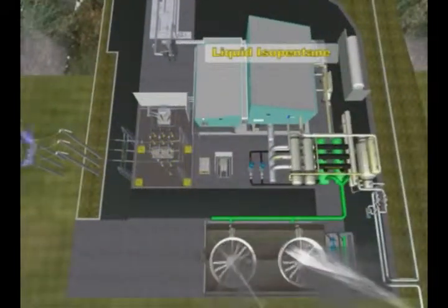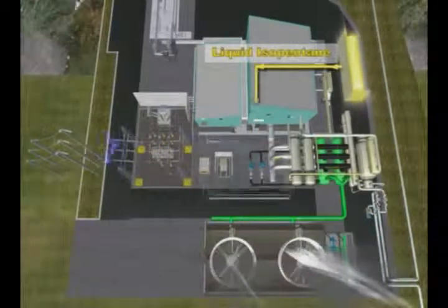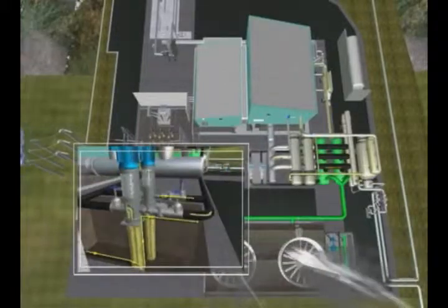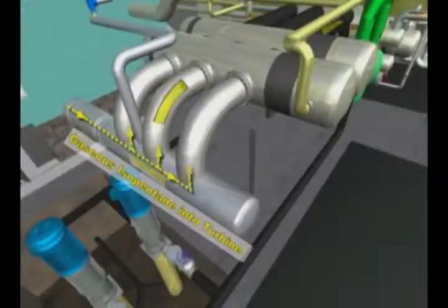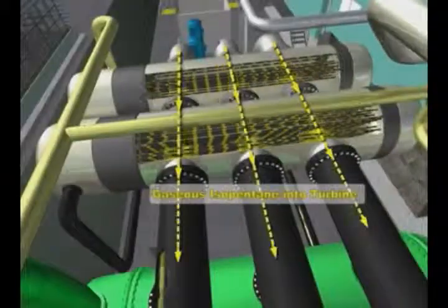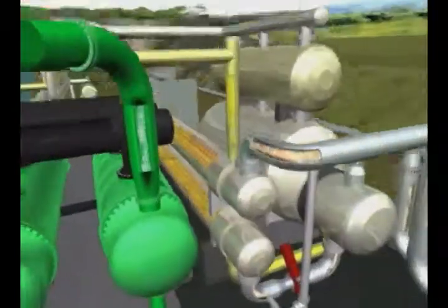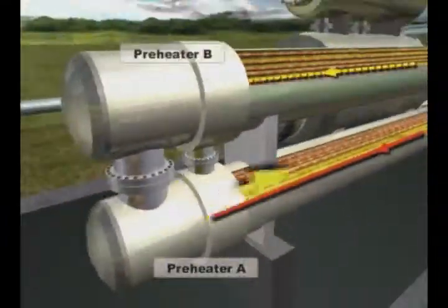On the other side, the isopentane starts its course, leaving the storage tank to a vertical pump, which is sent to the recuperators, where the vaporized isopentane, exiting the turbine, transfers part of its residual heat. Later, it enters the heat exchanger through preheater B and finally to preheater A, where the isopentane receives heat.